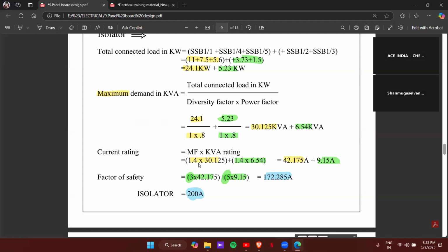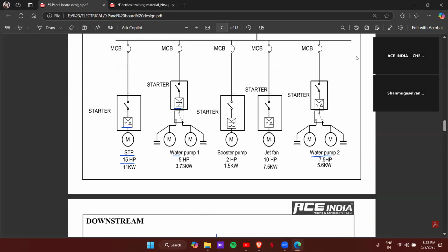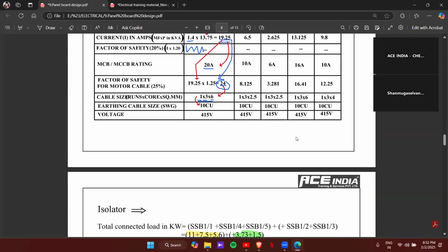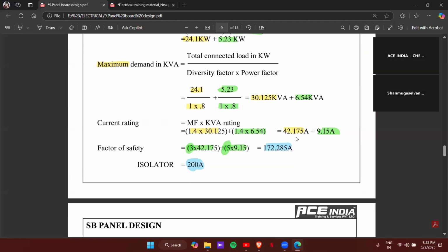Just a quick question, there is an additional requirement of increasing the motors. So even in that case, will we go with the same factor of safety? No, that one we have to check. If there is any scope of upgrading, you have to check that one also. Check the list, because we'll add spares also. Into this panel, we'll add more spares. Okay, so that's motor panel design.